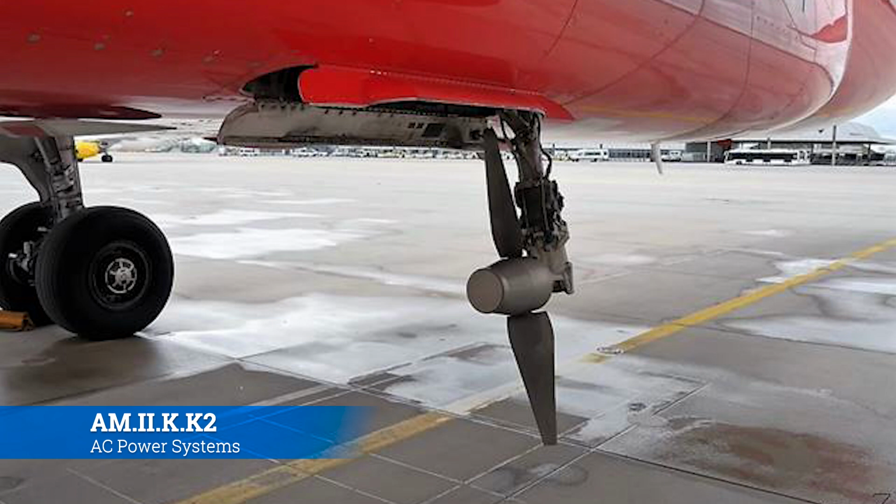However, on large aircraft that use a lot of power, they'll actually employ AC alternators. So virtually all transport category aircraft, like the 757, 767, 777, Airbus A380, they all employ at least one AC alternator driven by each engine. Now, these aircraft also have an auxiliary AC alternator driven by the auxiliary power unit. The APU will also have its own.